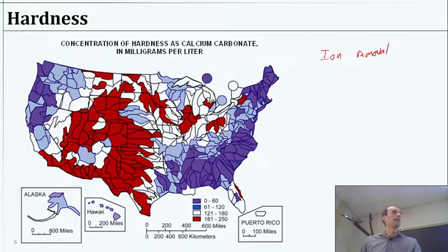But is that really practical? The question becomes, okay, we dug this well and we installed this system, and it cost a good amount of money to invest into that, but the water's not great. It's on the verge of, maybe you could use it, but maybe people wouldn't really use it. What do we do then? We've got $20,000 invested into drilling the well and installing it, something like that. Might be a little more. Well, do we just move and drill another one and hope, or do we tack on a $10,000 ion exchange system? Maybe that's actually more worth it. So there's an interesting question there. I don't have a direct answer for it, but I'm hoping that as a class we can at least have some idea there, and give some thoughts for how they might be able to navigate that.